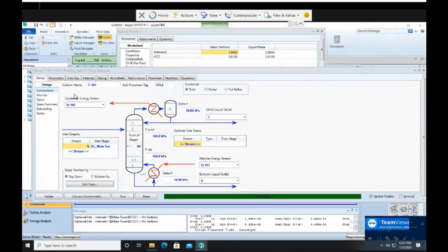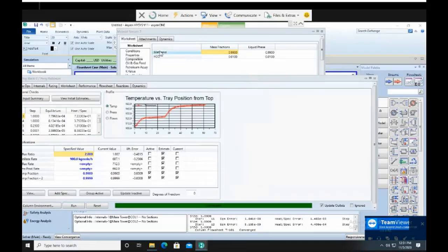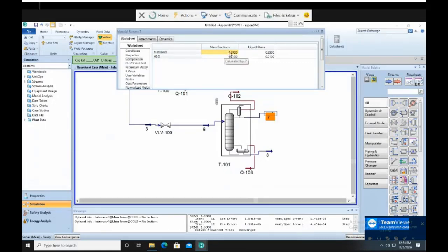So in this case, you know that you can change this. You can change the number of stages. But I was just about to change my pressure drop tadi. Pressure reboiler dengan condenser. So it will actually impact you punya product purity, but this is converged, so this is fine. So in here you dapatlah methanol you 0.99. You can actually do. So if your customer wants it to be 99.9%, that's how you do it now. Okay.